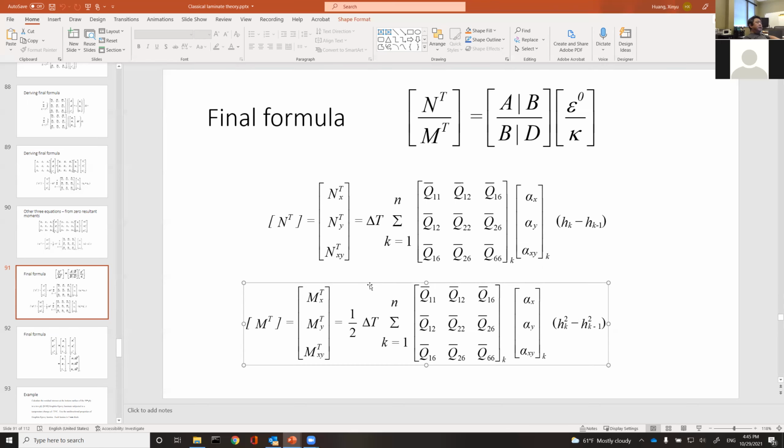That usually is somewhere between the curing temperature and the glass transition temperature. It depends, but it usually is high, higher than room temperature. It could be 50 degrees, 70 degrees, or 100 degrees above room temperature. There is a temperature where things are assumed to be stress-free.